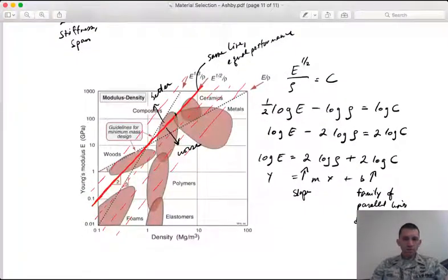Right, and so we see that for our beam, right, for a light, stiff beam, you know, the metals are actually disadvantaged, right, and so we see composites, right, there are some composites that we would predict would fall into our acceptable range, and then actually, interestingly enough, right, we would have maybe some wood that would fall into that category as well.